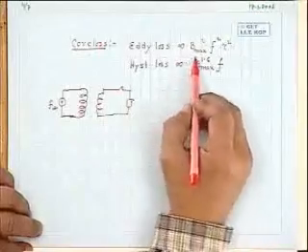In a transformer, you should remember, from no load to full load condition, do you think Bmax will change? Bmax will practically remain constant. Supply frequency is constant. Magnetic material volume is constant. So, the core losses remain practically same whether the transformer is operating under no load condition or under loaded condition.